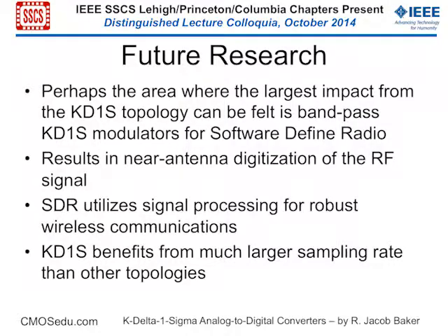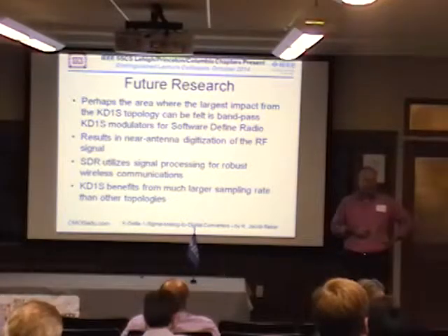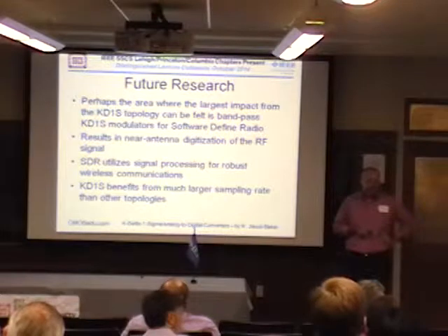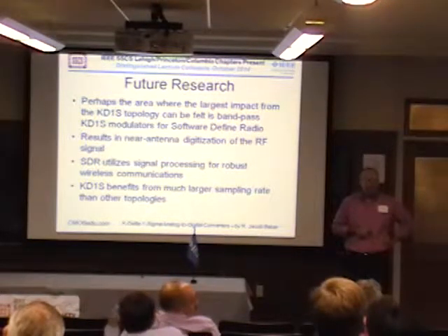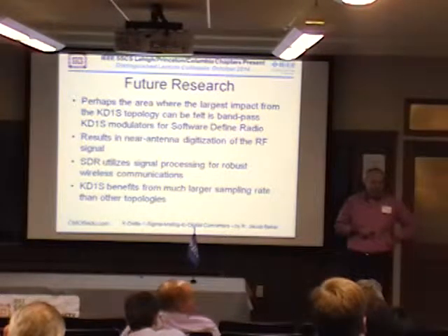Please. It was occurring to me, as I compare going at a very high clock rate with just one comparator feedback and then the lower clock rate with multiple levels of feedback, I'm trying to decide whether the kT over C noise will be identical by the time it's all done or whether there'll be some benefit.